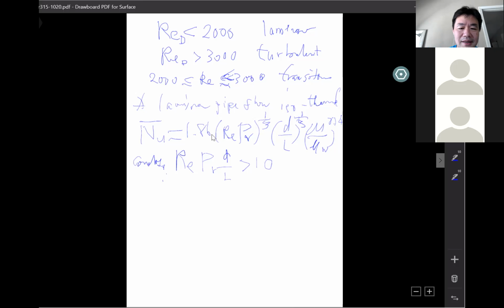So this is the laminar equation. So we have 2 equations, right? For laminar pipe flow heat transfer with isoheat flux and isothermal, okay? So you should be able to handle them, but sometimes in this type of problem, let's look at the example. In this type of problem, you need to consider the properties, at what temperature you receive the property. It will always be, that's why I ask you to do that Excel project.